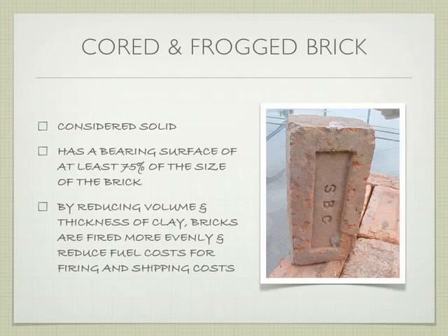And so this reduces the volume and the thickness of the clay. It allows the bricks to be fired more evenly, more consistently in the process, reduces problems during the firing process, because they're going to heat more easily. It reduces the fuel costs to transport these bricks to the site.